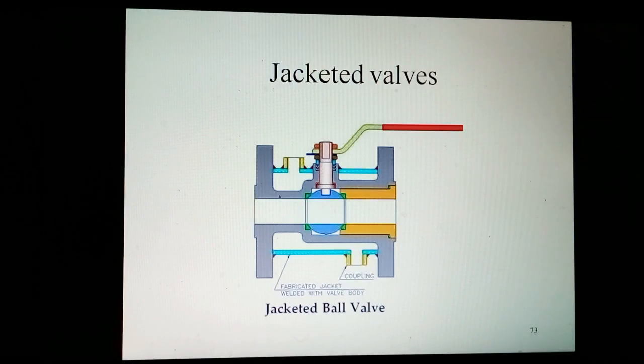The jacketed ball valve was very well designed to help the high temperature steam or oil flow over the valve ball and body parts to keep the media liquid. This applies especially to media like bitumen and liquid sulfur. In addition, the efficient flow of media is ensured through the elimination of pockets. Steam can be used as heating media.